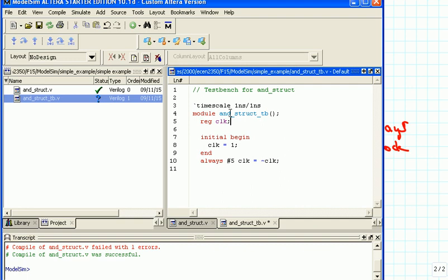and this register is going to be a counter. And we need 2 bits in that counter, so we specify this by the rectangular brackets there, going from 1 to 0. So that means that we have a position labeled with index 1 and a position labeled with index 0. And we're going to call this count. So that basically sets up 2 bits in a 2-bit register that we can use for counting.